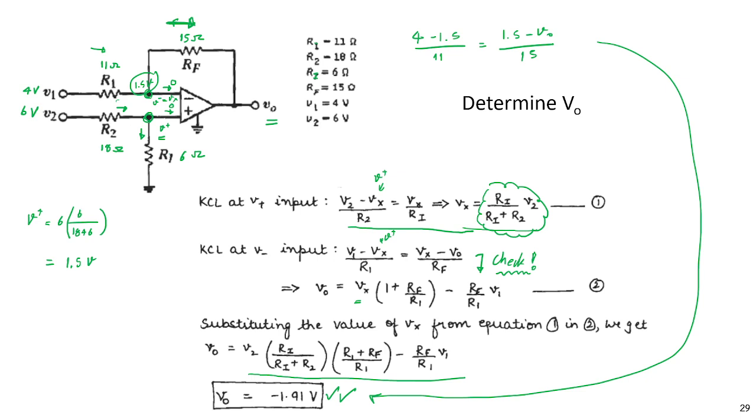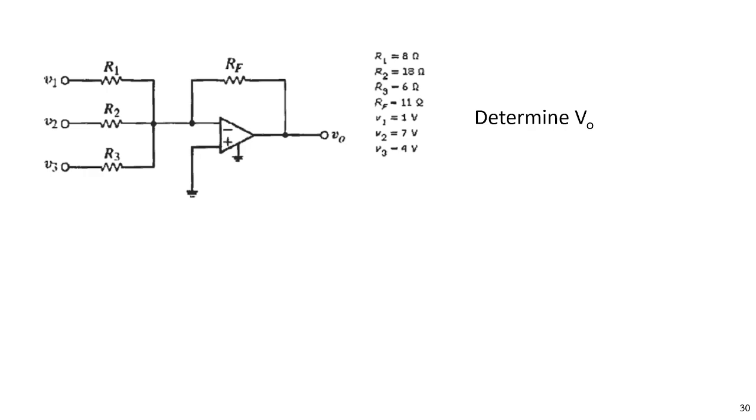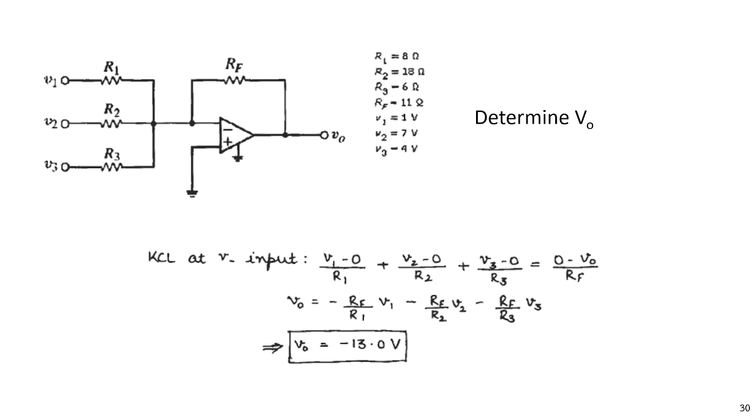Okay, easier, right? So in this case, they arrange the formulation without substituting the values. It depends on you; you can do it by understanding the main rule, which is that V positive and V negative are equal, and I in is 0. So you can use your circuit analysis knowledge to solve with the rules of the op-amp. Okay. I think this is the last, right? Okay.